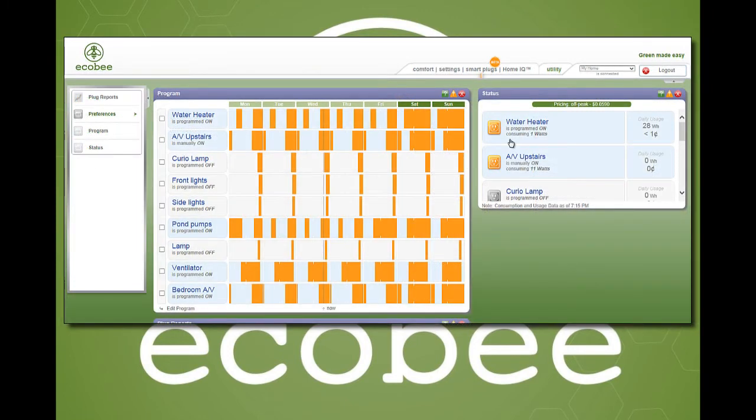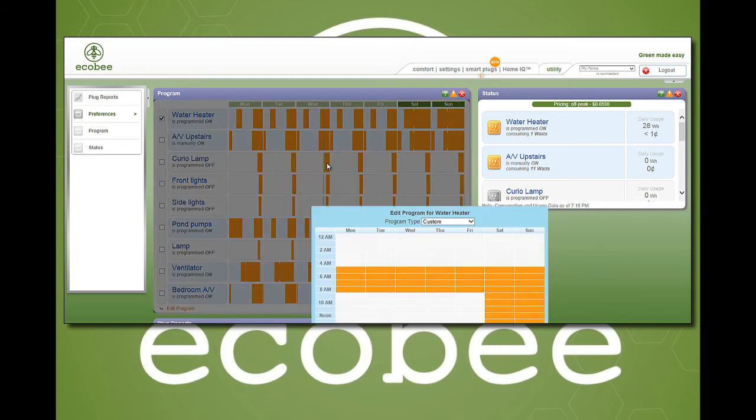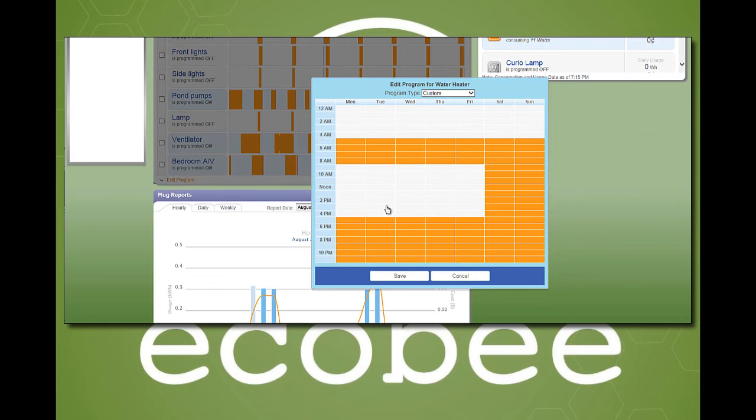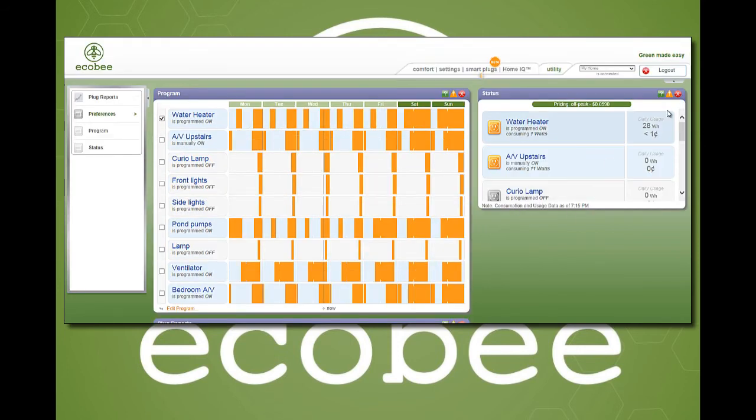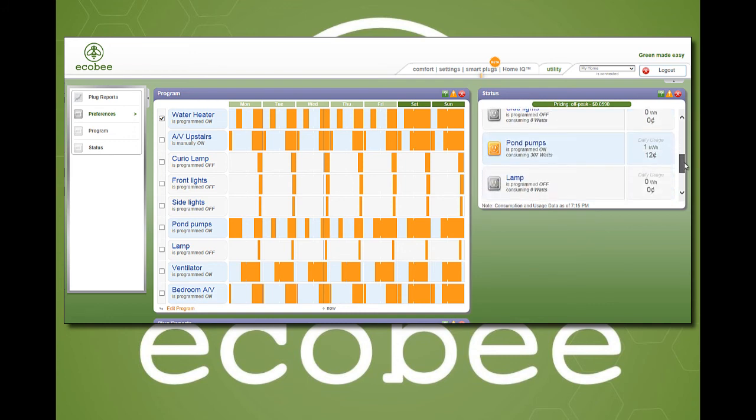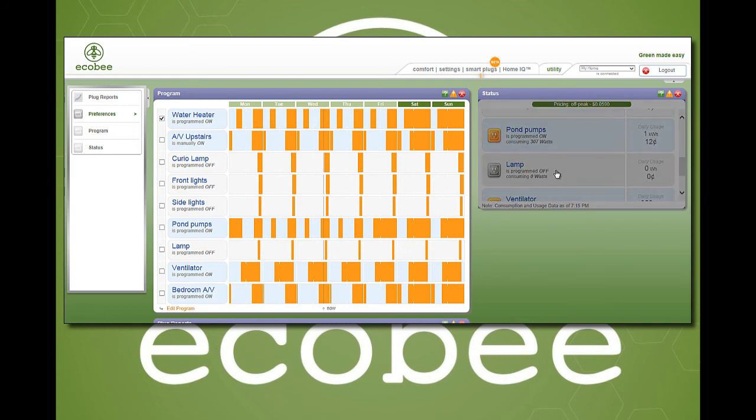If a user has Zigbee home automation configured on their ecobee, with ecobee smart plugs or aftermarket load controls added to the Zigbee network, the Smart Plug tab will appear. With smart plugs, you can have up to 32 devices controlled through one Zigbee module. Each device can have its own custom schedule, or each can follow the 7-day HVAC schedule. The status widget allows the user to turn on or off the plug and see what the current status is, and when it is on, how much power is being consumed through the plug.